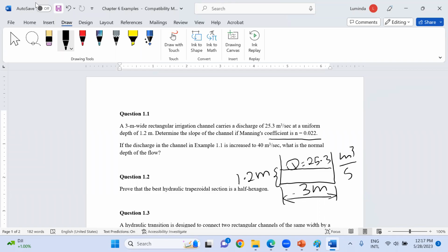If you go to the Manning coefficients, you will see that the natural canal also starts with 0.025 and goes up to like 0.035, right? So you can understand that the roughness coefficient is higher, so you can expect a reasonably high amount of head loss in this channel, right? By considering them, use the Manning equation to find out the slope. That is the first thing.